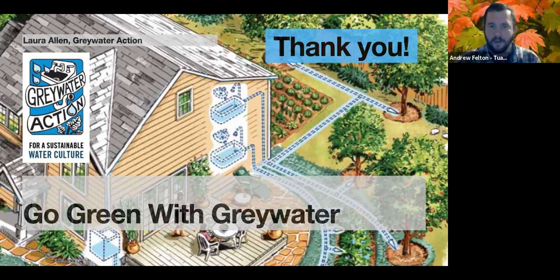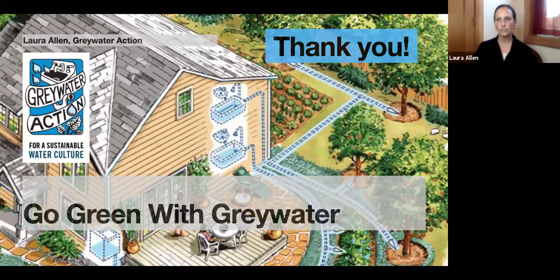Awesome, great. For a gravity-fed system, how much downgrade per foot would this person need, ideally? It's a 1/4 inch per foot. That's the standard slope. You could go, if need arises, to an 1/8 inch per foot. That's also allowed for drainage plumbing, but 1/4 inch per foot is typically what you're shooting for. Very good.